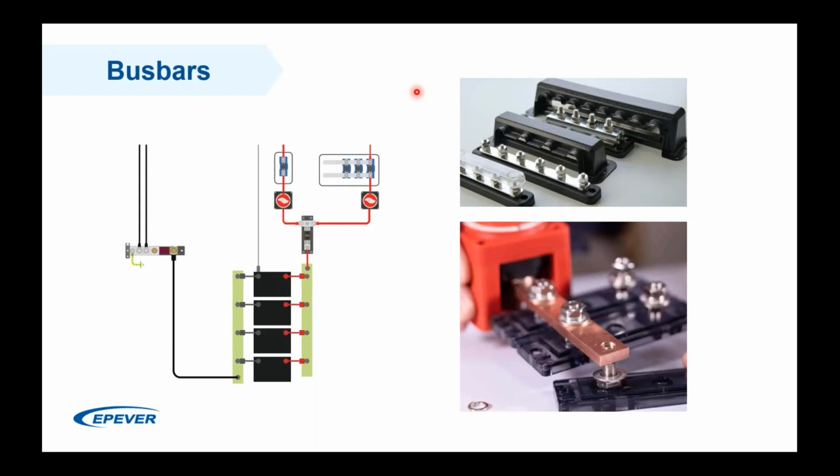You can buy a pre-made bus bar, or you can create your own. With a piece of cut and drilled copper or thin copper bar and a few fuse holders, you can create a DC distribution system. Again, for marine applications, you should use tinned copper.